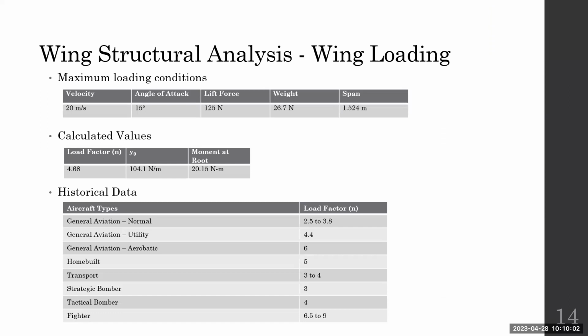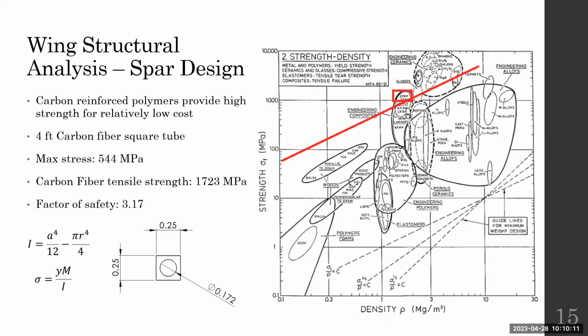Yeah. Let's talk about the carbon tube that you used as a spar. Do you know what type of carbon tube that was, like what the layup schedule of it was? It was a pultruded, just 0-degree fiber tube. So unidirectional.